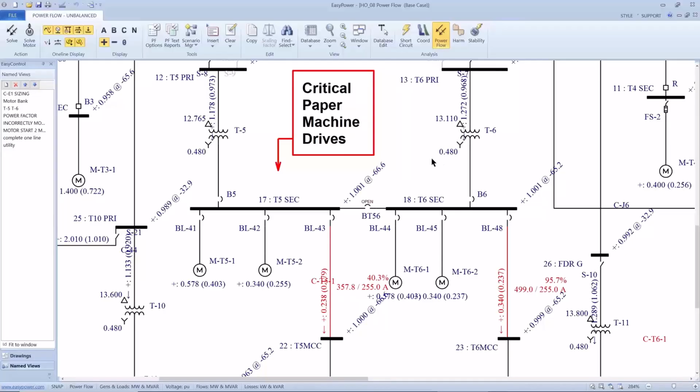So let's say for now, I'm happy with that, and we can go on about our business. Now we keep talking about power factor. One way to deal with it is to place capacitance near the load and take up some of the slack for the reactive current that's flowing to keep that load rotating.